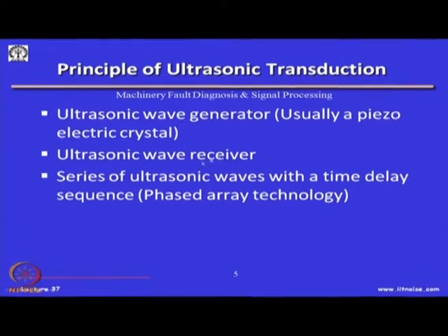And then we also have a receiver. Another technique is we can generate a series of ultrasonic waves in one go, many waves going in as an array, and they will get reflected back. This helps us quickly find out the defect.